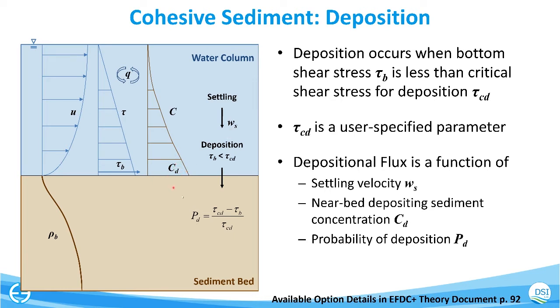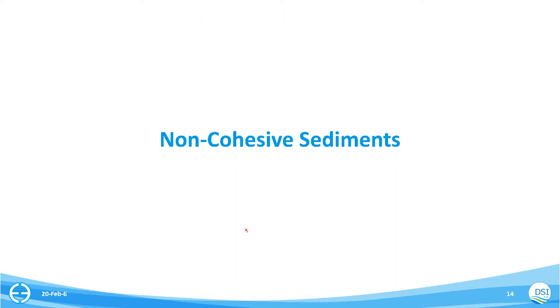here, and the probability of deposition PD, which can be calculated based on the relationship between the critical shear stress for deposition value and the flow bottom shear stress. Now we'll see how the model simulates the non-cohesive sediment behavior.